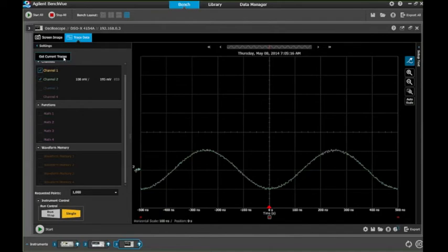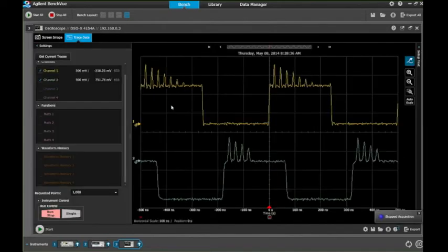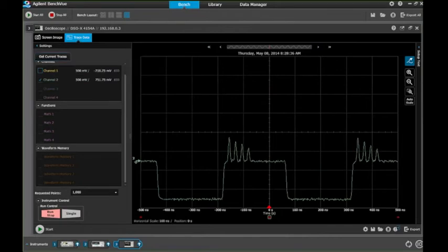And from the scope, I can grab the actual data points from every trace. So what I want to do now is simulate the DDS-based signal with our 4 points. I'm just going to focus on this second channel here, and I will try to simulate this signal with my Trueform generator. So let's go ahead and do that.